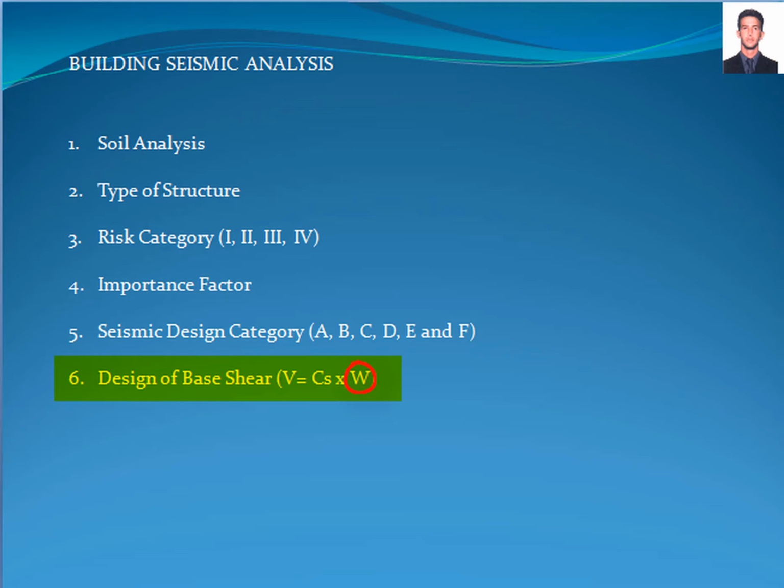and the effective seismic weight is the total weight of the structure plus the dead load added from the construction materials incorporated into the building, and shall include a minimum of 25% of live loads in areas used for storage, as required in section 12.7.2 of the American Society of Civil Engineers standard.